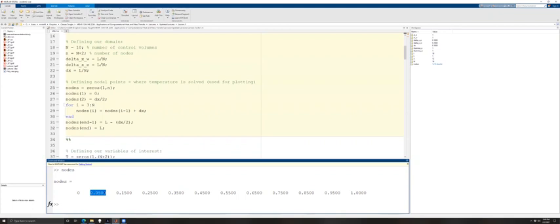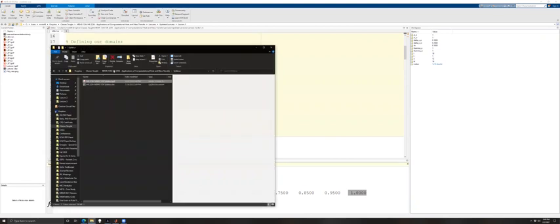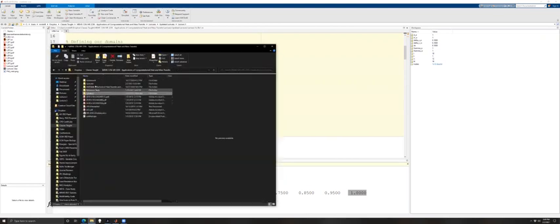Our second node is the node that represents the center of our first control volume, which is 0.05 meters. Now, in this situation, we have a value of dx of 0.1. So each of our interior nodes is increasing by an amount of dx until we hit our last node of 0.95, where we add half a dx on to get to our 10th node. And I will pull up a picture that illustrates this.